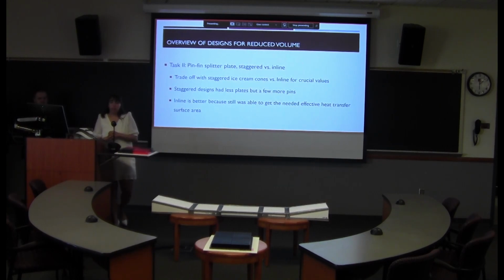So we did find that there was a trade-off in the staggered ice cream cone designs with inline pins for the crucial values of pressure drop and heat transfer. So the staggered plate design then had less plates in it, but it had more pins. So we decided eventually that inline was in fact better because we were still able to get the effective needed heat transfer, and we were able to maintain a good surface area.